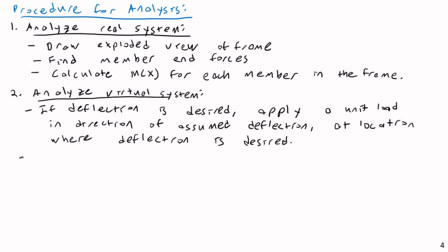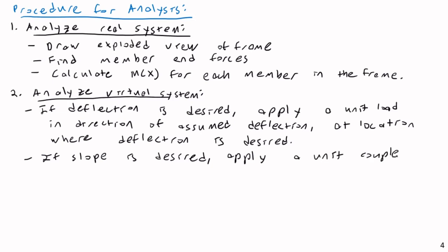And if slope is desired, we will apply a unit couple at the location where slope is desired. So really, this is the exact same thing we've been doing previously with beams and trusses.